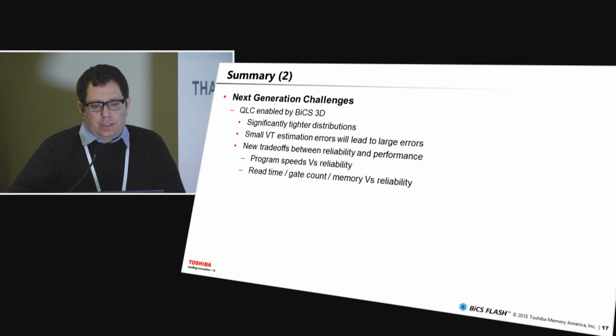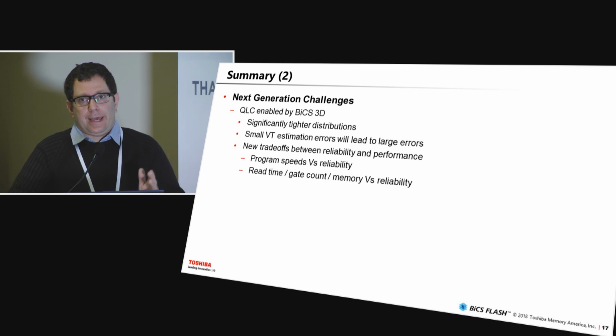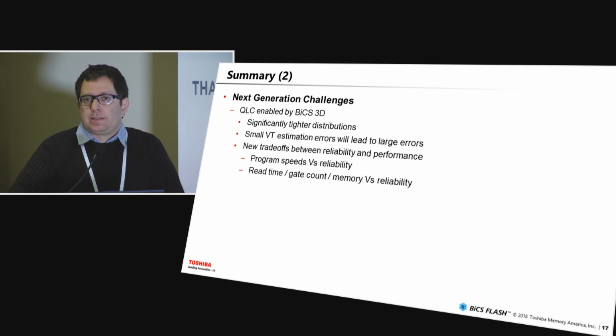The next generation challenges include QLC devices, which are enabled by 3D NAND devices. The reason is that, again, you have much tighter distributions there. Small VT estimation errors now will cause a large bit rate coming out from the NAND. So you must be much more accurate and must adapt your VT threshold much faster.